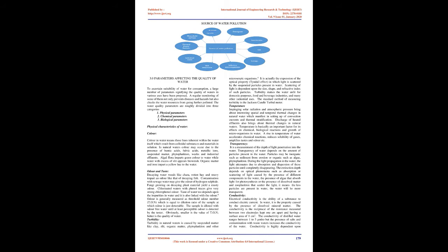Contamination with sewage water may give the odor of hydrogen sulfide. Fungi growing on decaying plant material yield a musty odor. Chlorinated waters with phenol traces give a very strong chlorophenol odor. Taste of water too depends upon the impurities in water, and it is also linked with the odor.